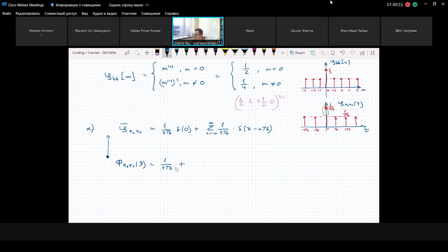And if we do this, we get another sequence of delta pulses. We have 1/4 TB times 1/TB times the summation, mu goes from -infinity to infinity, of delta pulse f minus mu times 1/TB. This is the Fourier transform for the sequence of delta pulses.